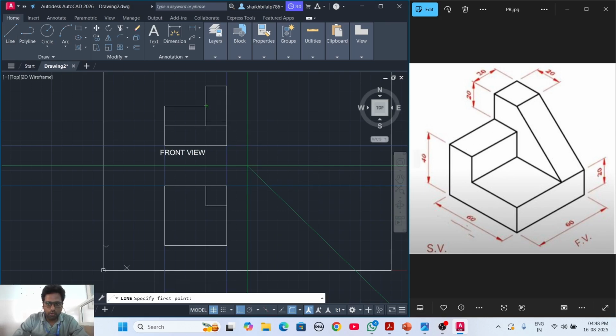Now this wall, backside wall. Let's go from this. This we have already drawn at the 20. So I am just selecting this and giving horizontal direction. I am not putting a dimension, it's actually 40 mm, but if I don't put a dimension, that is also fine. Just extend it anywhere horizontally, and after that we can use the trim command.